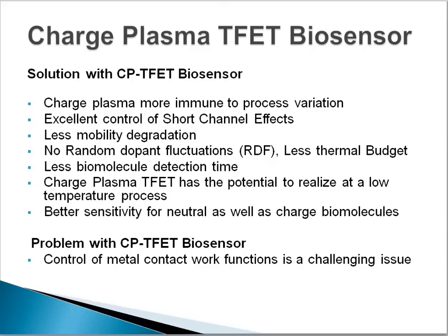This means that even if there is a small change in the doping and the thickness, it will not change the electrical attributes of the device. Second, excellent control of the short channel effects. Third, less mobility degradation. Fourth, no random dopant fluctuation, because we do not require high doping techniques, diffusion and ion implantation, so the thermal budget of the device is low.